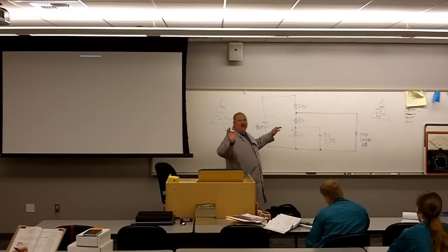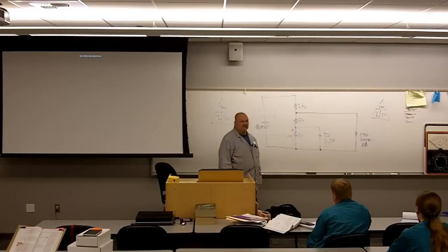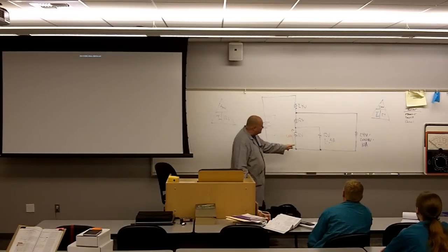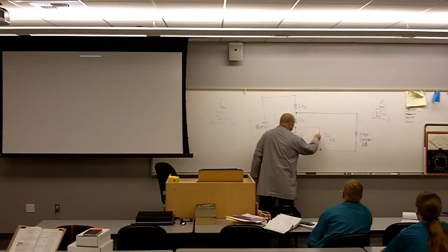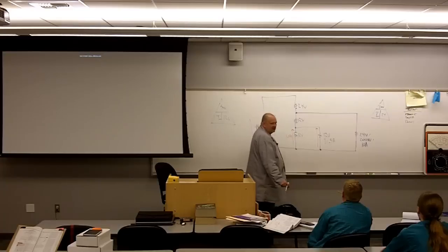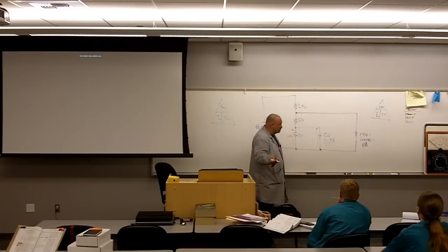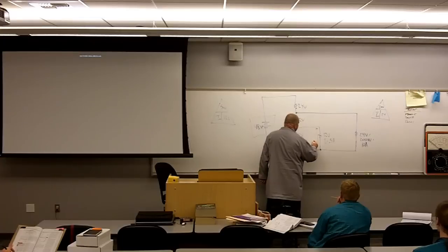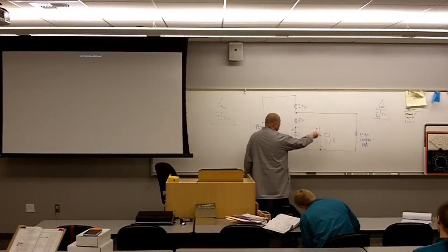Right there, we just unlocked the entire circuit, because what we've got here is 1.05 amps coming up out of this node. How much current do we have coming up through here? Where'd that number come from? The paperwork. Or your calculation, if the paperwork left out the current demand; you know it's a 5-watt radio, and as long as you can prove it to somebody. So we called that 0.5. So we've got 0.5 amps coming up through here.